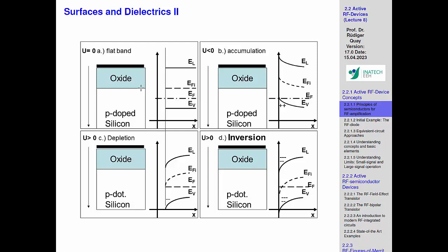So this is something we have in mind. And then what we want is that with a capacitor, which we are effectively building, we are either attracting or pushing away holes or electrons. So this is the idea. Capacitor, what you learn in school normally, there's a field effect which allows you to deplete or to accumulate carriers near this interface. So in the case of accumulation, you would accumulate the holes here.